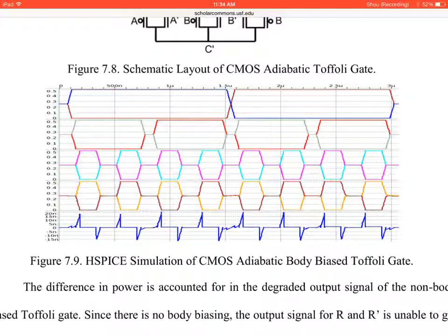One of the contributions of my dissertation was that if you hook up a circuit, like a smart card, to an oscilloscope, you can use the instantaneous waveforms based on the spikes, which you guys now know enough to understand. If you design CMOS circuits in a certain way, you know how much the power consumption is going to go by if you know how the circuit works.